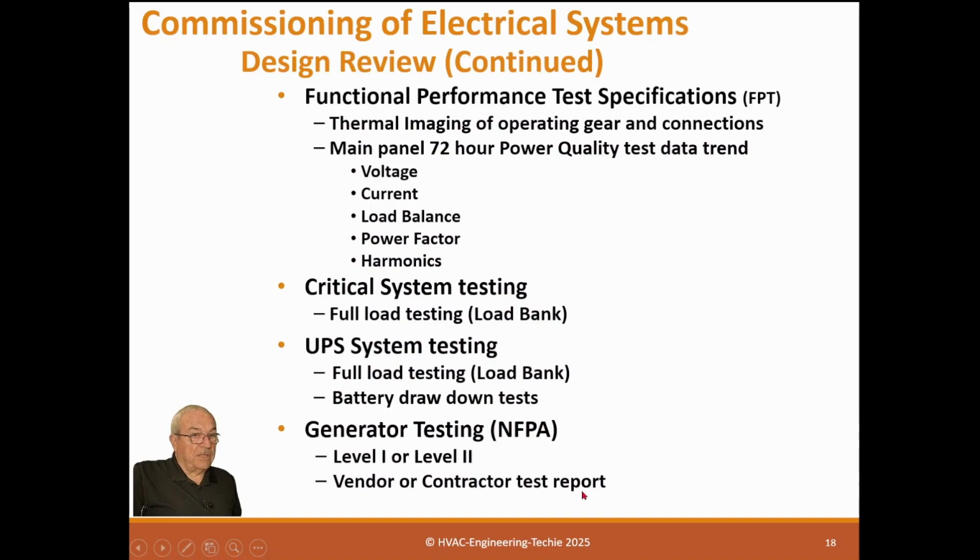Vendor or contractor test report. Now, normally all this stuff is done by a contractor. It may be a testing contractor. One thing the spec should say, in these testing specs, is whether this job requires a third-party independent testing agency. Many specs do. They require a NETA certified testing agency.